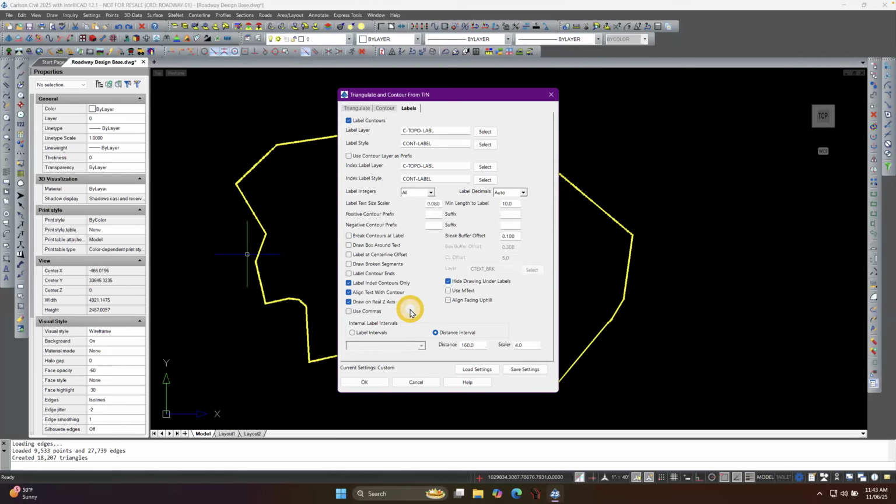Maybe you don't have but the one contour on there that's gotten labeled, so you don't know which way uphill is. You just know what that one elevation is. So if you have that drawn so that they face uphill, then you would look at the map and position yourself such that you are reading the label. Then if you looked up from the map, you would be looking uphill instead of downhill. All right, so it's just another little indicator. Again, I've never really seen it used, but that's what its intent was.